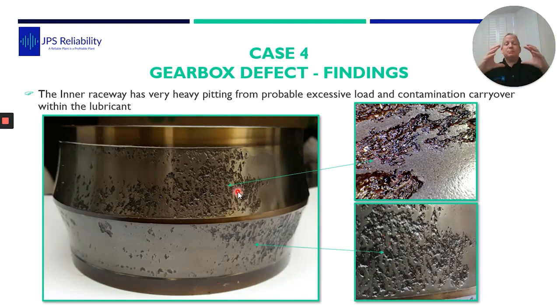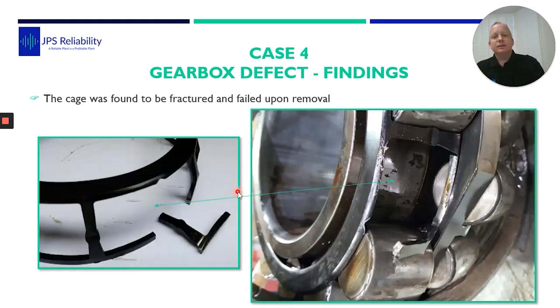When we took it apart, before we took it apart, we marked up all the bearings: drive end, non-drive end, top, bottom, and where the weights were, more importantly. And it so happened that on the furthest part of the weight swing, where you get the load, the shock, it's in the same place, because the weights are bolted to the shaft and they don't move. They turn with the shafts. So the same point in that inner race is under the highest stress all the time. And again here, on the opposite side where you got some carryover, you can see it started to damage the race. So we had an inner race defect, picked up beautifully with vibration analysis.